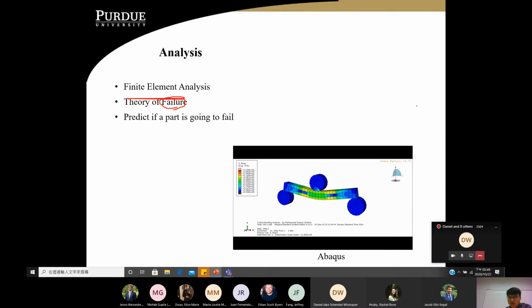You can see some color gradient changes, and you can showcase where the forces are mostly concentrated. That's all. So do not over-interpret it as saying this is the place where it is going to fail. No, it is not. All the conclusion you can draw is simply about the stresses concentrating on that part. So for example, if you're confused, right over here you have a 3-point bending, and you're applying forces over here, and then you have a support area, right?